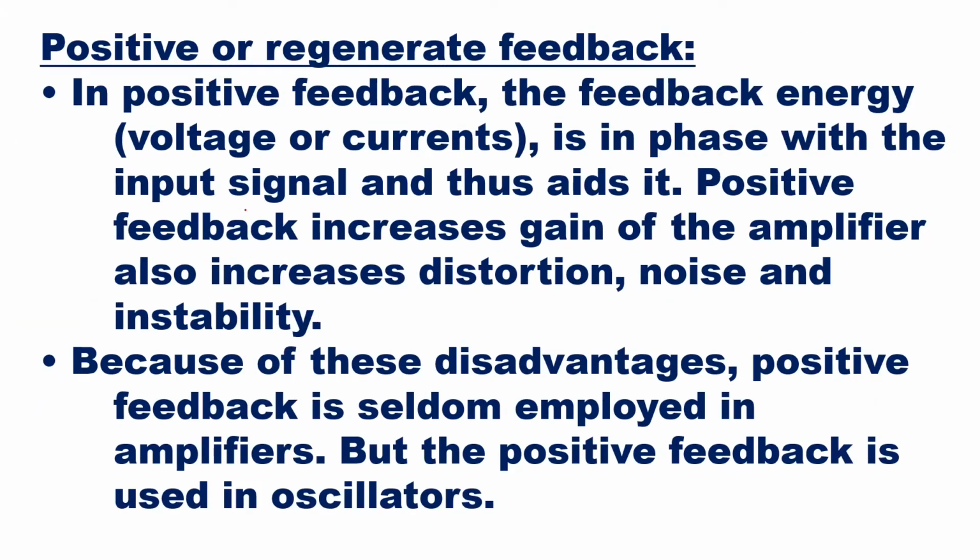Here positive feedback is also called regenerative feedback. In positive feedback, the feedback energy, that is voltage or current, is in phase with the input signal and thus aids it, helps it. Positive feedback increases the gain of the amplifier, and also increases distortion, noise, and instability. Because of these disadvantages, positive feedback is seldom employed in amplifiers. It is less used in amplifiers, but positive feedback is used in oscillators. This is the conclusion of what positive feedback is.